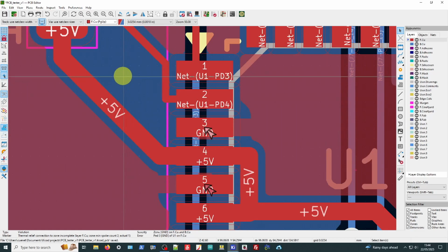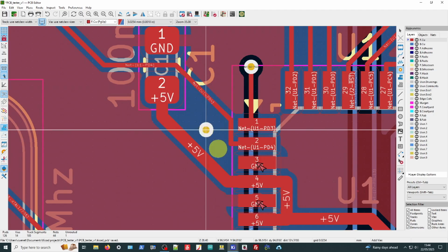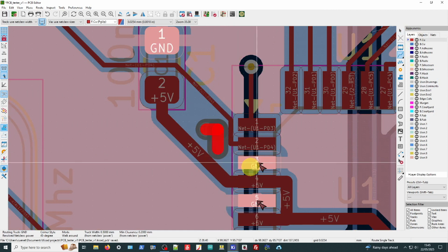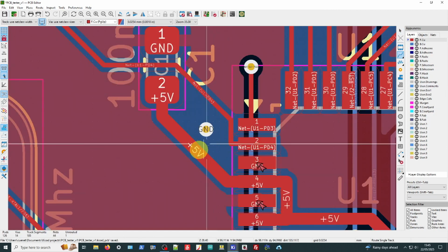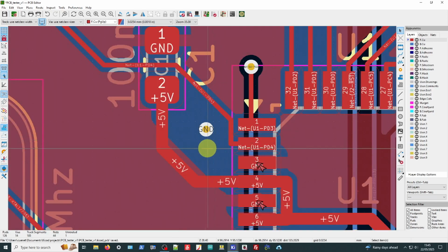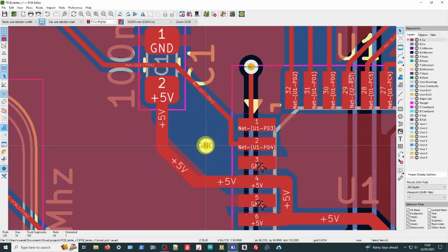So what we can do there is simply add a wire here, like that, and then we can take a manual trace from there to there, and this will connect through to the blue side or the other side of the board, and that should give us a ground. So let's just select the manual route, and we can hopefully, right, it's not going to let me do that, so we're going to have to shift this track first. Let's pull him down here, and this is where the manual editor comes in. You know, let's put him somewhere down a little bit closer there. The manual editor in KiCad is actually very good.